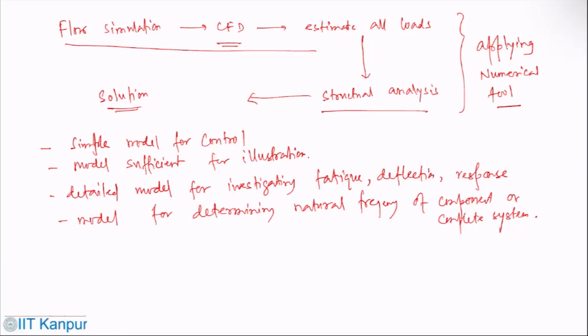So when we come to the structural response, the structural analysis can be done in different ways. The best way is using the complete finite element method. That means you will have the whole geometry gridded and then run the finite element analysis for structural responses and things like that.